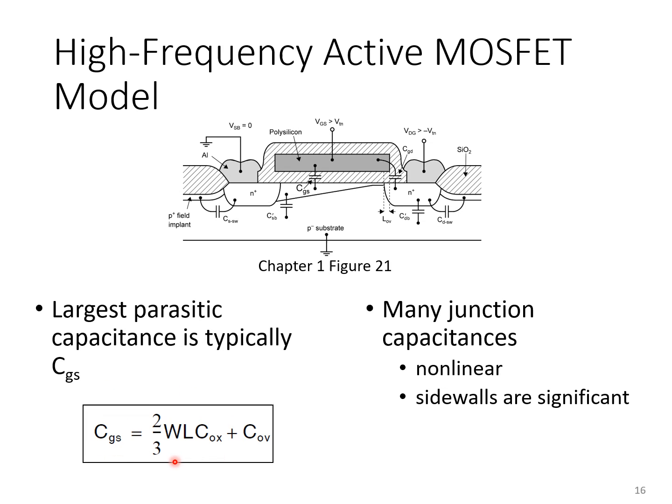So in this expression, you'll see how CGS depends on the area of the gate, W times L, as well as Cox, which is the specific capacitance or capacitance per unit area of the gate. It in turn depends on the dielectric constant of this oxide, typically silicon dioxide, and the thickness of the oxide layer. So this sort of looks like just straight up expression of the area of a parallel plate capacitor, but we've got this 2/3 term here because it's not a simple parallel plate capacitor.